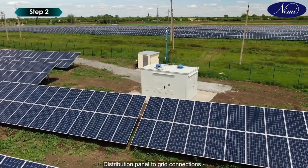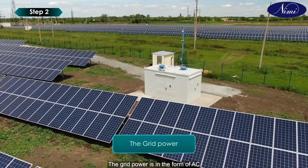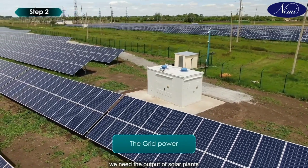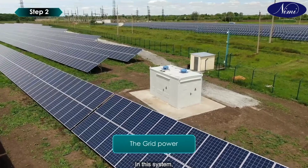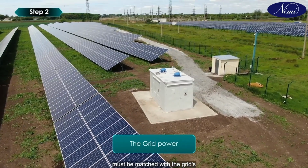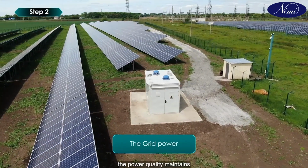Distribution panel to grid connections. The grid power is in the form of AC, and if we need to supply power to the grid, we need the output of solar plants to be similar to the power of the grid. In this system, the most important condition is that the output frequency and voltage must be matched with the grid's frequency and voltage. And also, the power quality maintains the grid standard.